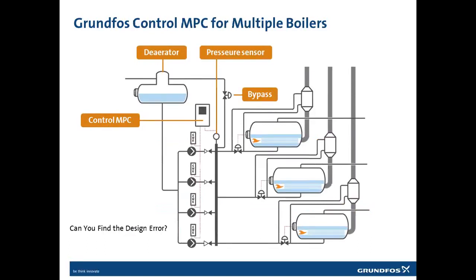It would be, like shown on this drawing, from a condensate tank directly to the deaerator. Normally in many applications, we see that on-off pumps are used, and that works perfectly fine. But if we want the full efficiency of our deaerator, then we can have maybe up to 10% higher efficiency by running the condensate pumps as speed control pumps, because we will have a continuous and constant degassing of the water.